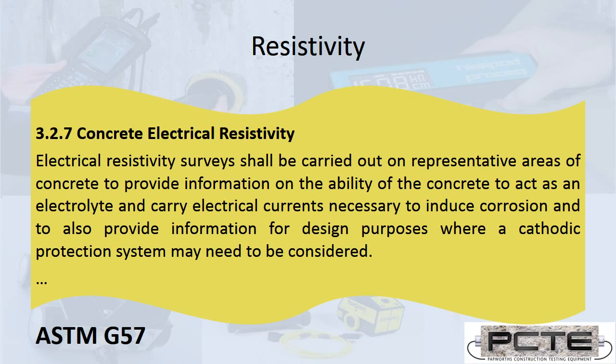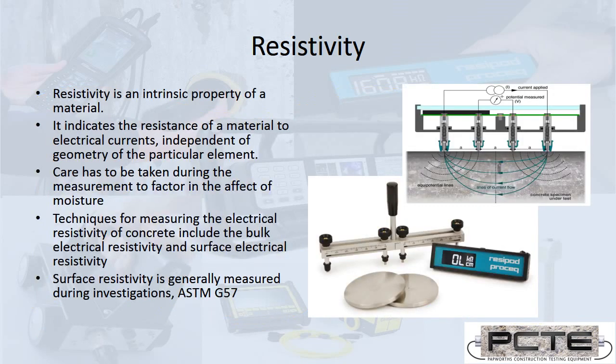So these are typically used in looking at the rate or the presence of corrosion of reinforcing steel in a concrete structure. Resistivity is also extremely important for input to cathodic protection design. The resistivity is the inverse of conductivity. The more conductive the concrete substrate, the more quickly corrosion can occur. It's typically measured using either in situ measurement using a Wenner probe method, a 4-point resistance probe.